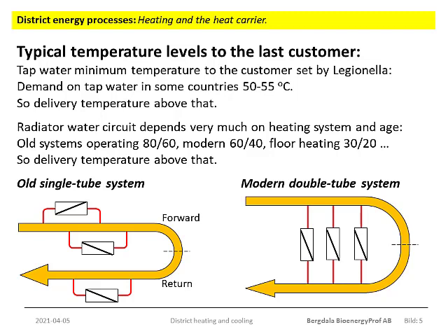For the second thing, hot water for the internal heating system, there will be no sanitary aspects, since this water is intended never to escape from the system. But then there is a huge difference from old wall-mounted radiators that may demand 80 degrees to heat the house, and a modern floor heating system where some 30 degrees is sufficient. So the customer farthest away must be supplied with district heating water that meets these demands. And that holds for 365 days per year, 24 hours per day.